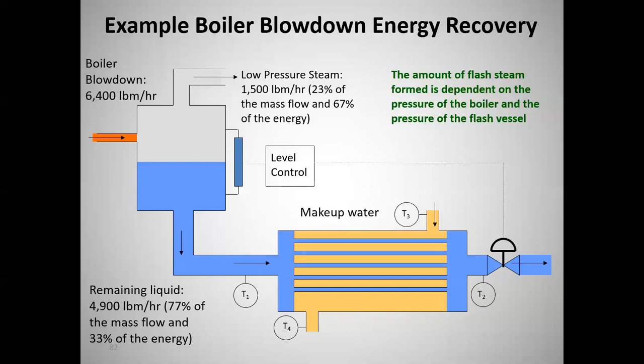Okay. Yeah, so you're right on track. You're just one component upstream. It's possible, but I'm not aware that the tanks really fill up that much. That heat exchanger has small tubes and passages. And absolutely, because that stuff was concentrated when it came out of the boiler, and we're going to flash off 23% of it. What happens to the concentration in the remaining 77%? Well, it's even more concentrated with crud. Absolutely.